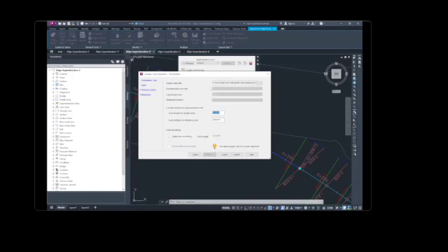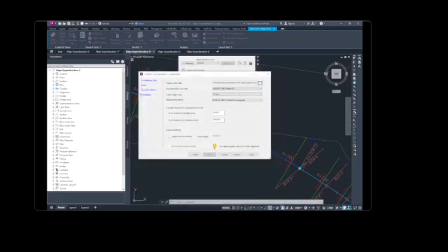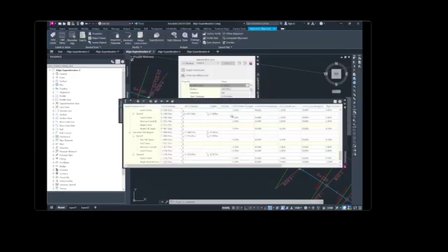And now, once we are in attainment in the design criteria, we're gonna select the standard, AASHTO 2001 Emax 6, and then in the parameters, apply curve smoothing selected, curve length 30. Click Finish. In the Superelevation Tabular Editor window, examine the superelevation values for curve 4.